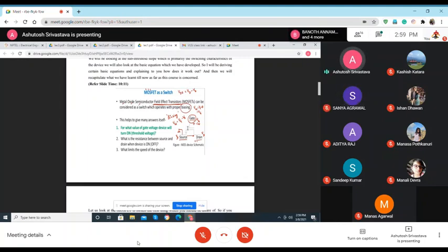So if you are able to make this region switch from holes to electrons, then only will there be flow of charges from source to drain, and that can be regulated by putting various external biases like the gate bias, the drain bias, and so on.